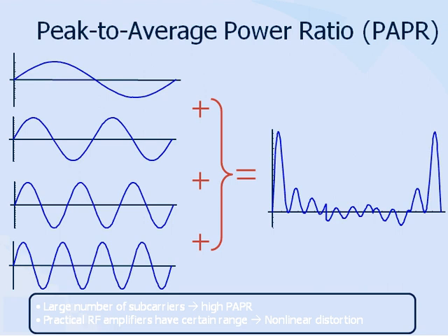In case of inter-symbol interference, even if no one is moving, because of the multipaths, we have some signal arriving directly at the UE. Part of the energy will probably get reflected from some other obstruction. So then we have a delayed copy. Even if the user is not moving, there will not be any Doppler, but even in that case, we will have interference. So the F1 subcarrier frequency we are not changing. It is the same subcarrier frequency.